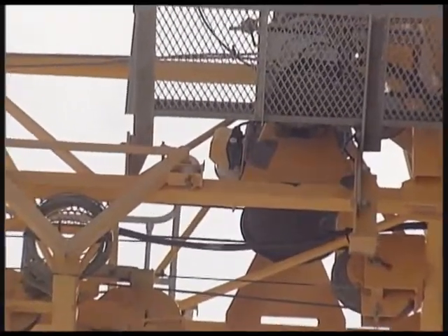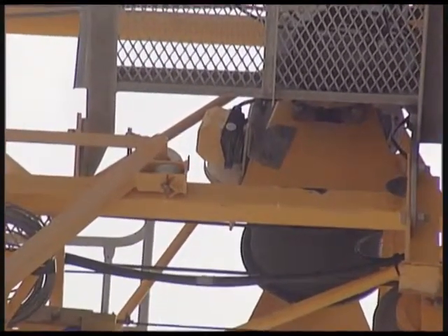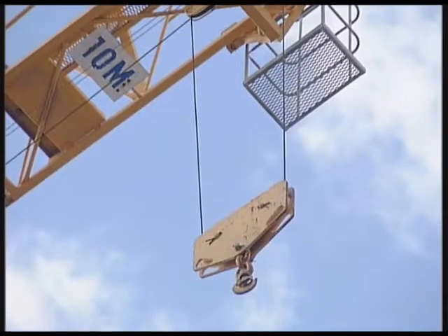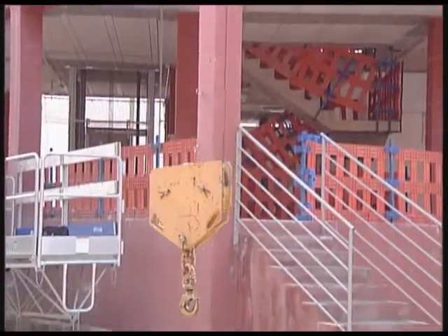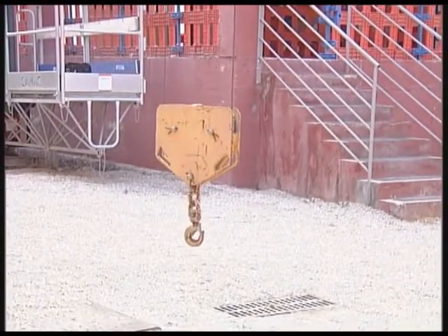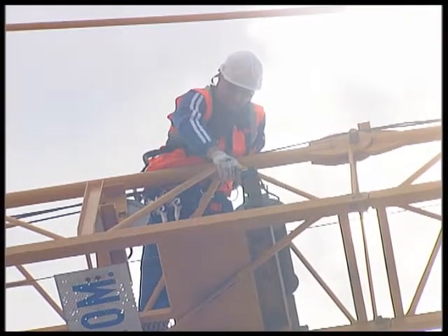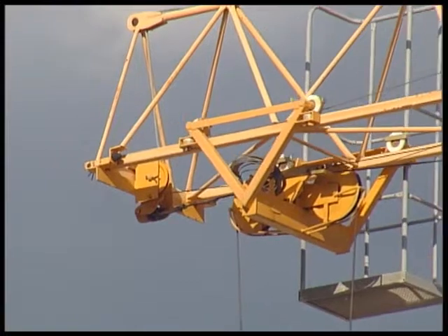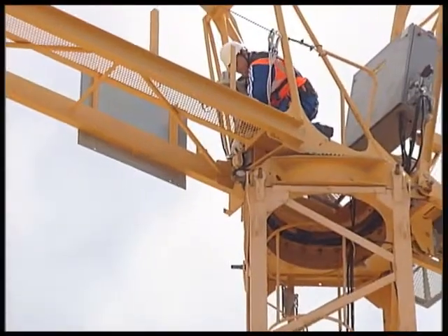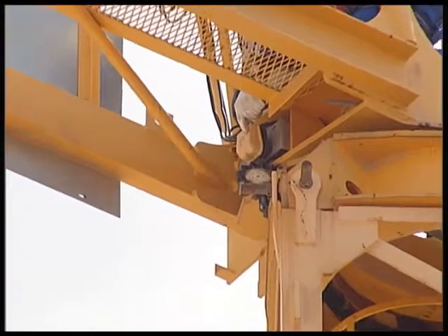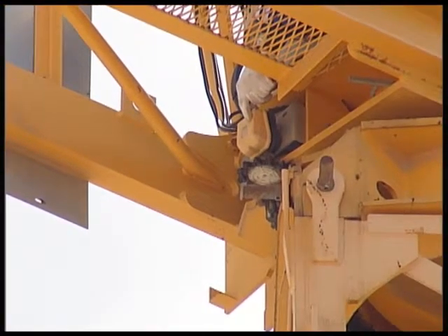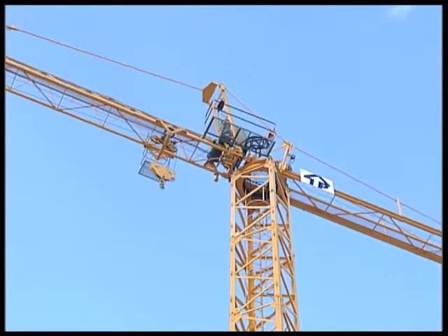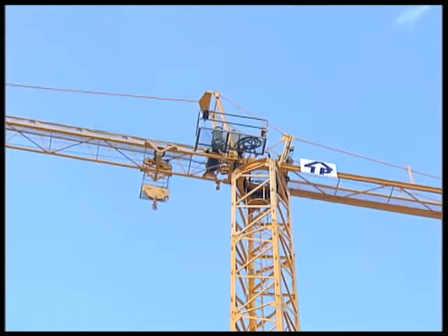Travel limiters. Height limiter. Device that prevents the hoisting and lowering of hook over the pre-established limits, thus preventing the hook hitting the trolley or touching the ground. Travel limiter. Device that prevents the trolley from over-traveling the pre-established points on the jib. Slew limiter. Device that limits the number of turns that the turntable can slew in either direction, so that jib and counter jib power supply cables are not subjected to excessive torsion.